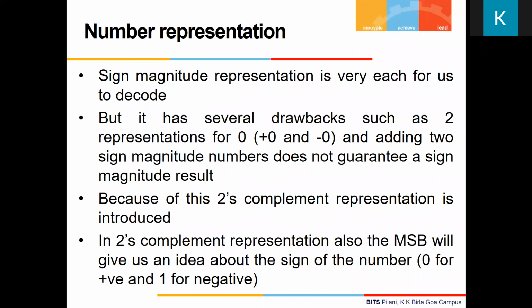But using weights, we will have to do multiplication also. In the case of multiplication, 2's complement is not very efficient. So in multiplication, maybe signed magnitude is better, in the sense that it takes fewer FPGA resources.